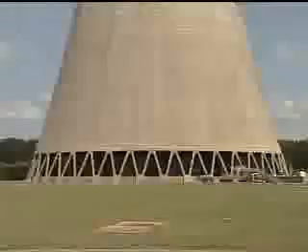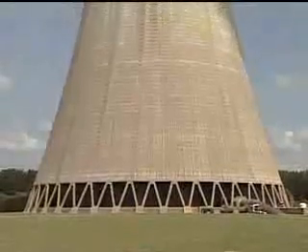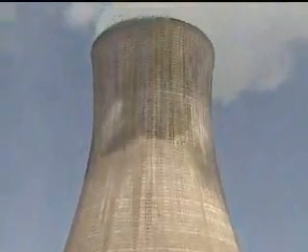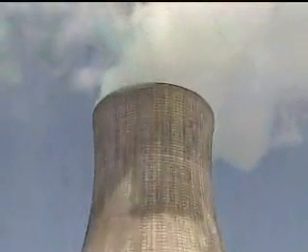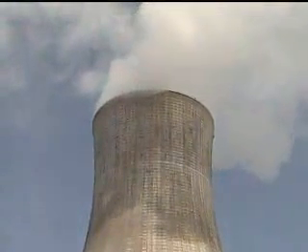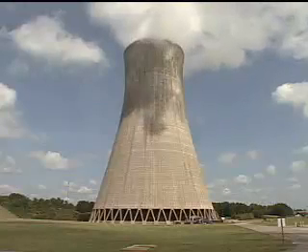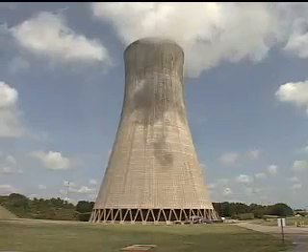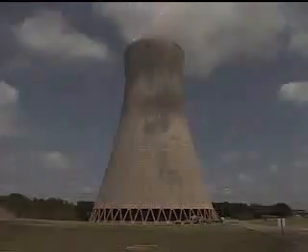The flow of air through this area cools the water by convection as well as evaporation. During this process, the air is heated and begins to rise. The chimney design accelerates the flow of air up through the tower and thus increases the overall airflow. Atmospheric pressure pushes more air through the tower to maintain the airflow that cools the circulating water.